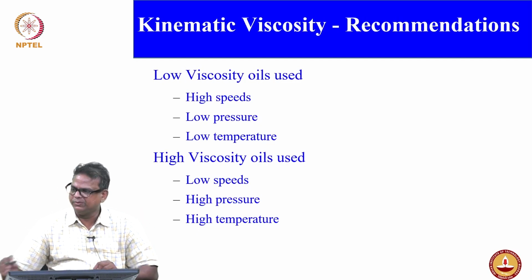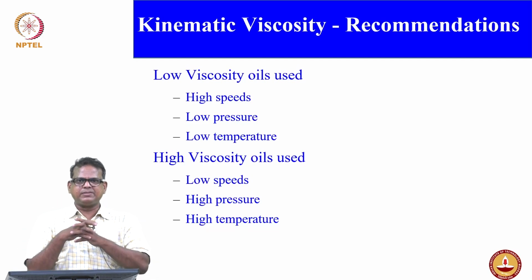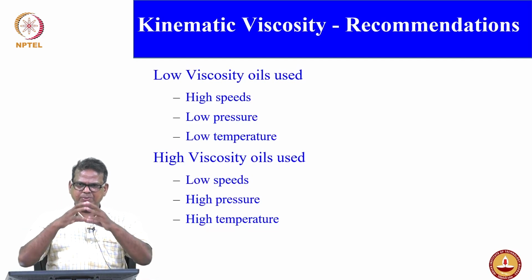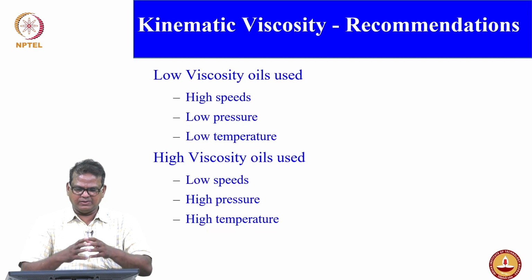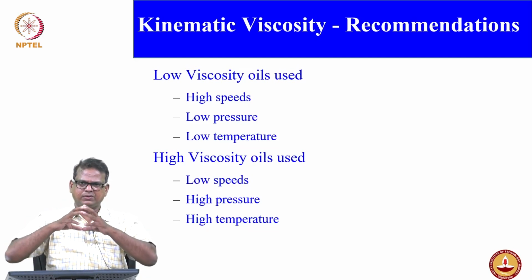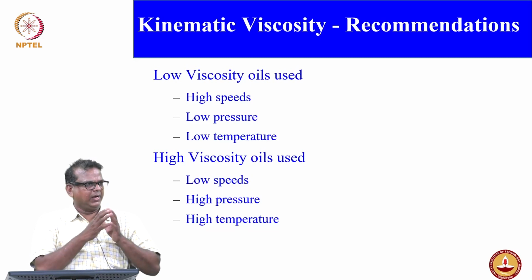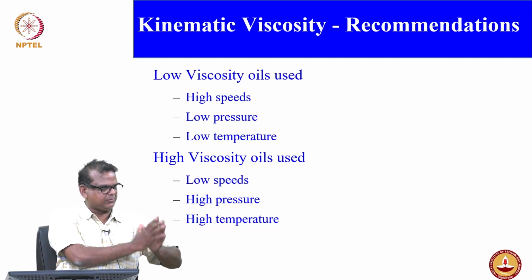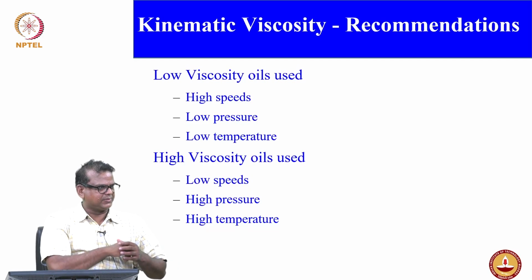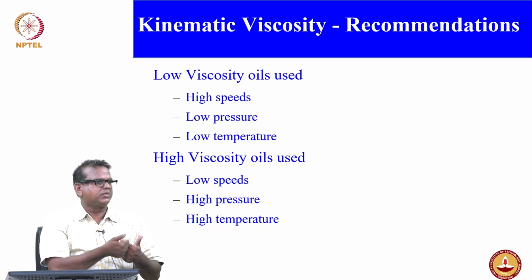Remember I said earlier also, it depends on the speed. If you have a higher speed gearbox, you should go for low viscous oil. If you have low speed, then you can go for higher viscous oil. The higher the viscosity, the more expensive the lubricant.